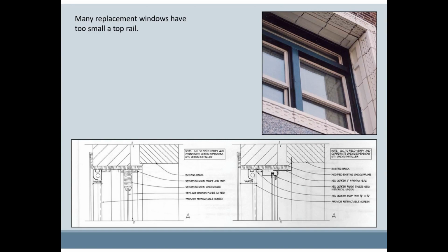A thin or skimpy top rail is typical of many aluminum window installations, but a better match can easily be achieved by adjusting the size of the window and altering the installation detail. The details at the top of a window remain visible even as other details are diminished in importance due to the sightlines of windows higher up on the building.